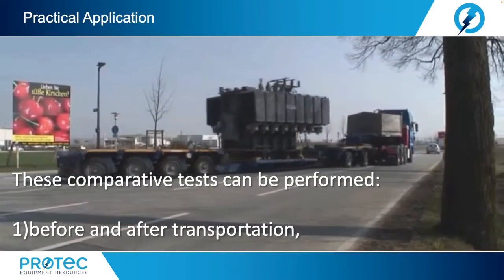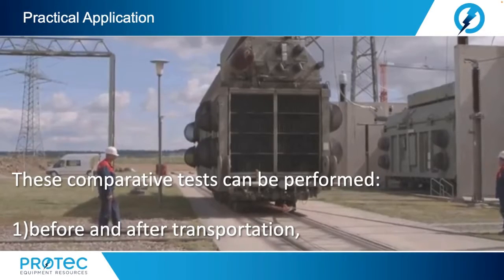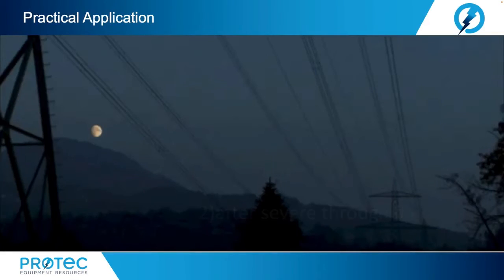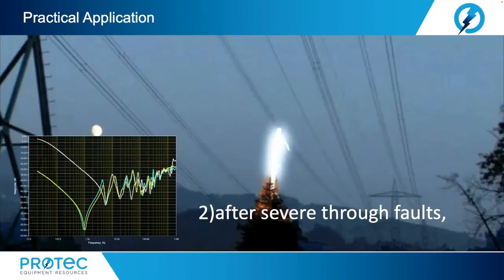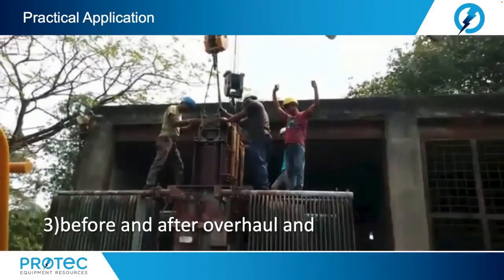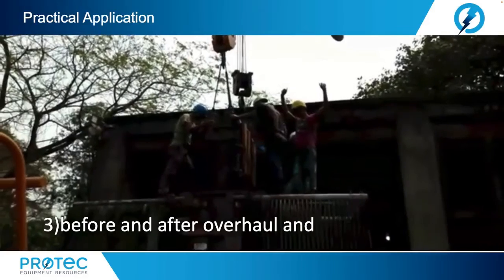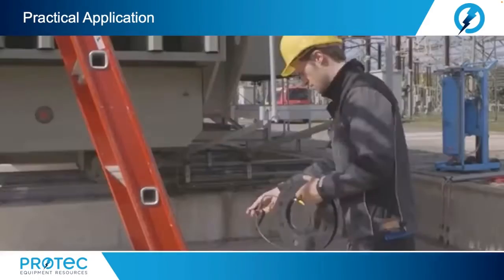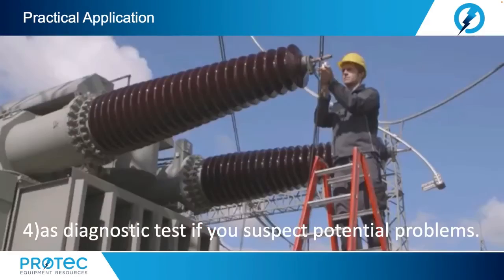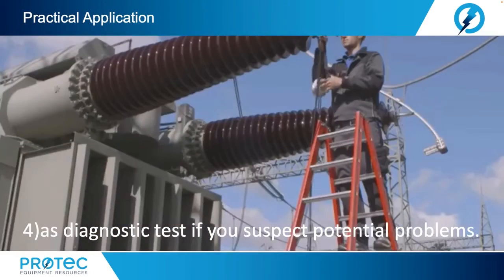These comparative tests can be performed before and after transportation of the transformer. After severe through faults. Before and after overhaul. And as a diagnostic test if you suspect potential problems.